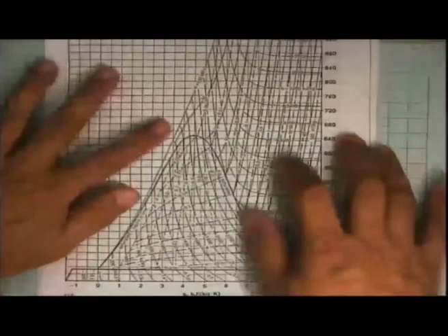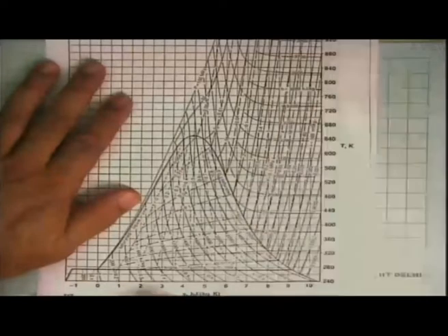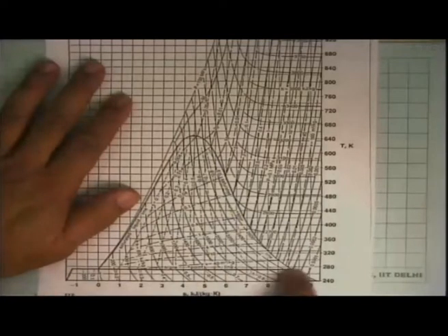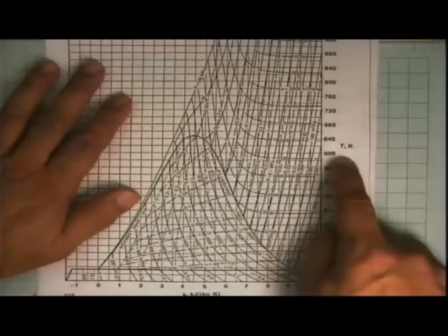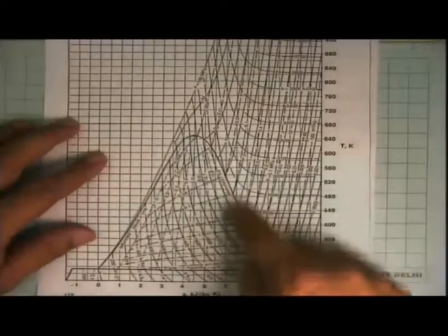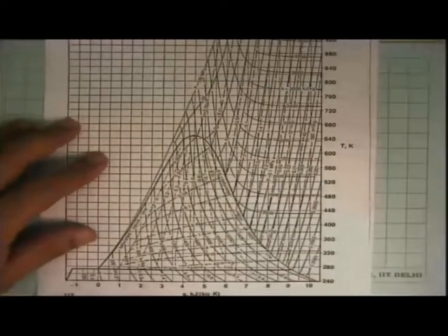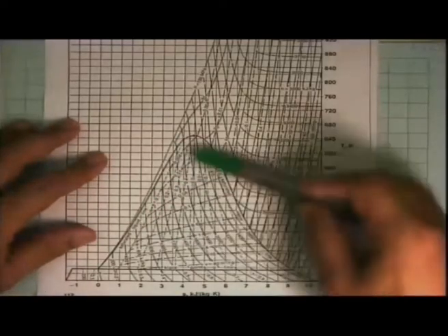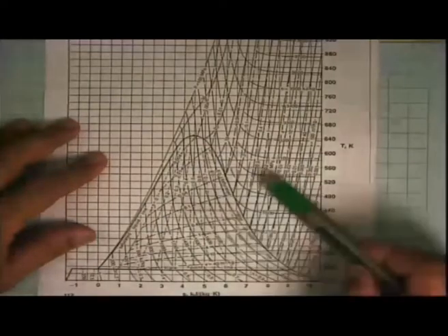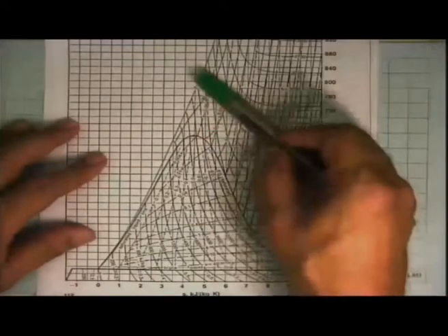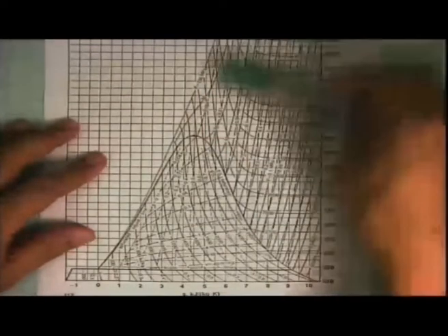Okay, you see a lot of lines over there. This is specific entropy. It is 0 here, which is saturated liquid at triple point. This is the triple point line of water, and this is temperature in Kelvin. So this is for water. And the shape of the dome is like what I qualitatively showed. And inside this dome, you have the same thing. X is equal to 0.1, 0.2, 0.3, constant dryness fraction lines going that way. Then you have P equal to 0.1 megapascal, 0.2, 5, 10, 20, 100 megapascal. These lines are going up there like that.